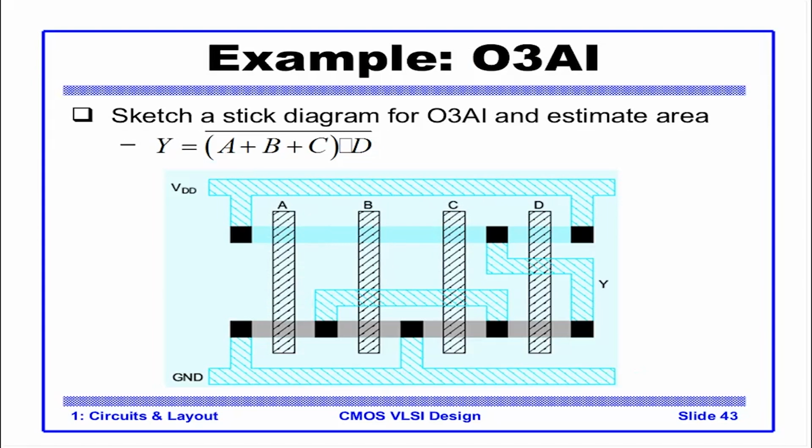One quick observation you could make is that you now see more taps on the NMOS when compared to PMOS. So you could say that the NMOS circuit requires more parallelism compared to the PMOS network. Since if the network is series, it would require fewer contact taps. If the network is parallel, since the parallel network needs to be connected to VDD and GND, each transistor gets connected in the parallel network, so you will see more taps in the parallel network, right?